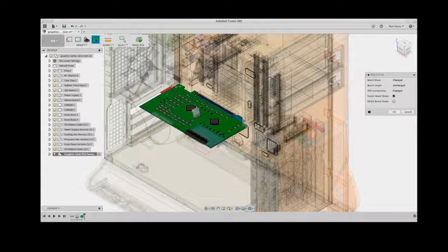Okay. Yep, and we can see that Fusion isn't updating the traces and the board routing. We can see the footprint of that component still hanging out where it was. So something to note here is when we go to the Eagle board shape, we see that the PCB components have changed there, and they're kind of just floating out in space where we have the Fusion board. And Fusion keeps two board shapes, but only one copy of the PCB component positions.